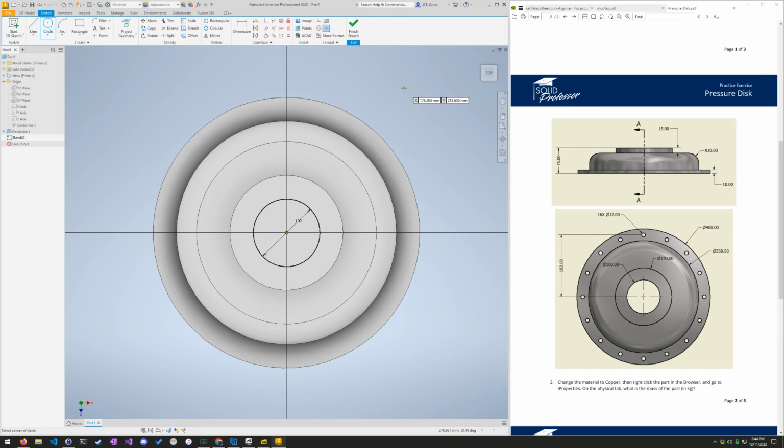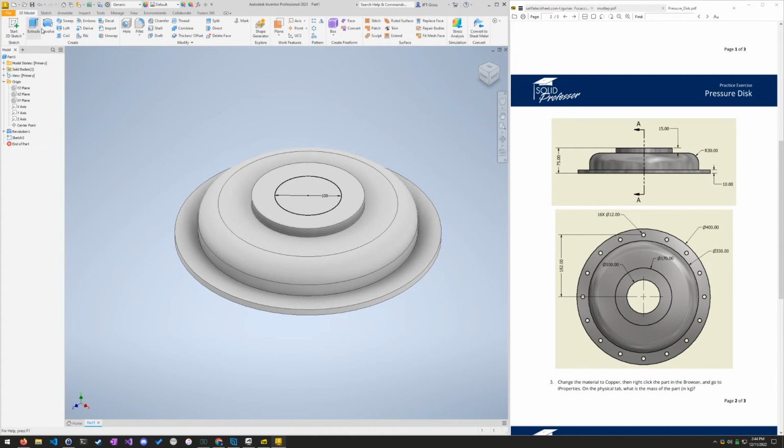That's all we need for that sketch. And it's fully constrained because I put the number in while I was drawing it. So easy. Extrude all, through all. Make sure it's cutting down, which it is. Perfect. Now, the only thing that's missing here is the circles.